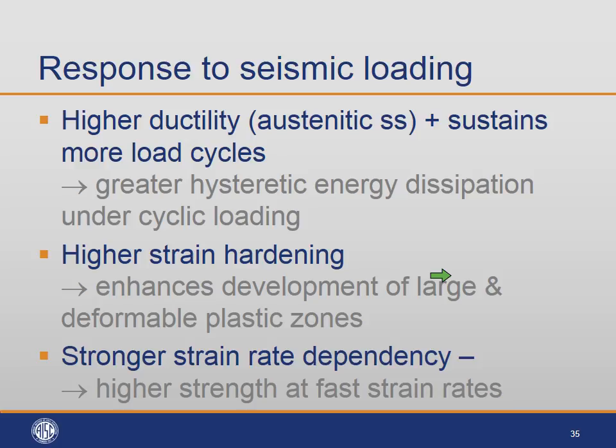So what's the response to seismic loading? Well, you can see that the higher ductility leads to the ability of stainless steel to sustain more load cycles, and this means that there's greater opportunity for hysteretic energy dissipation under cyclic loading. Secondly, the strain hardening enhances the development of large and deformable plastic zones. And thirdly,